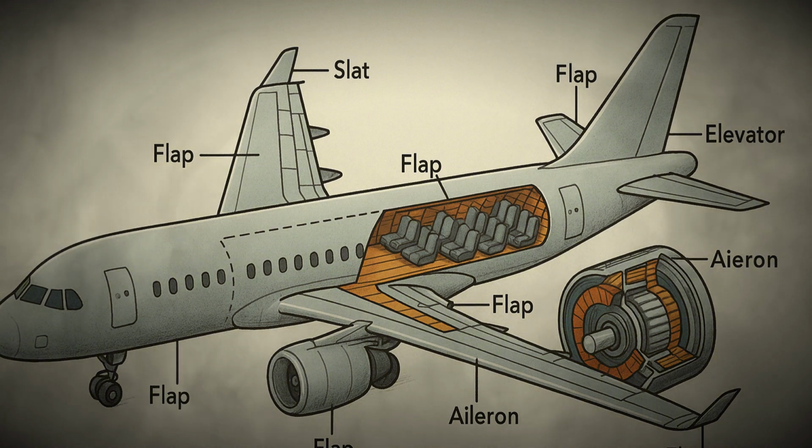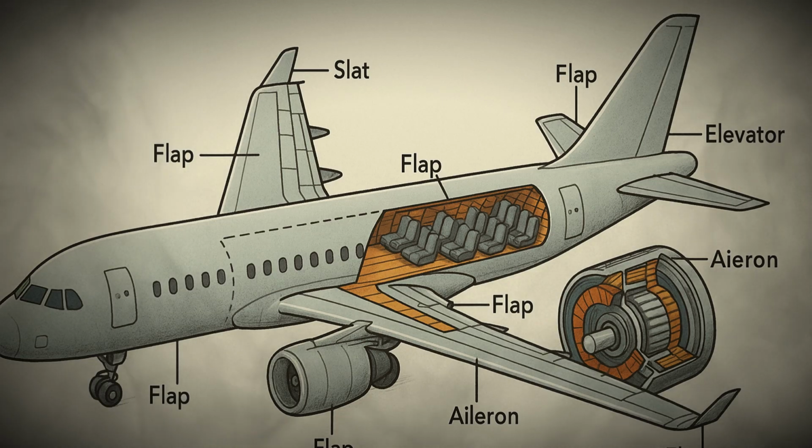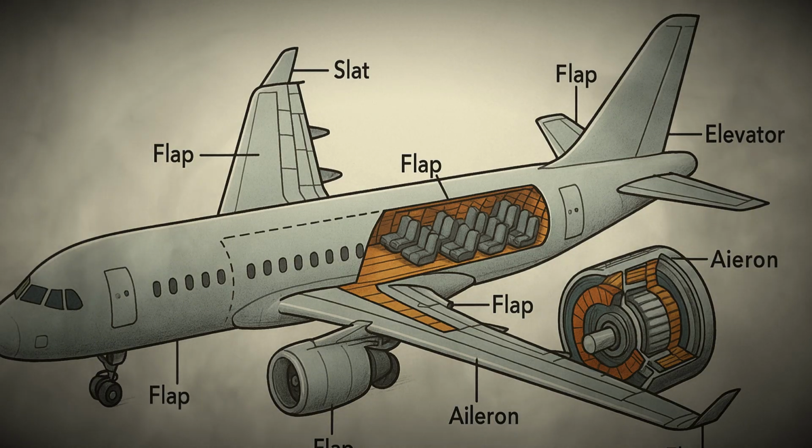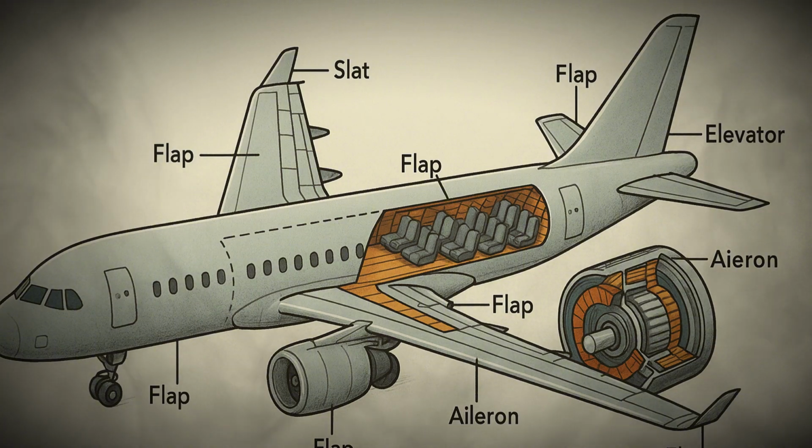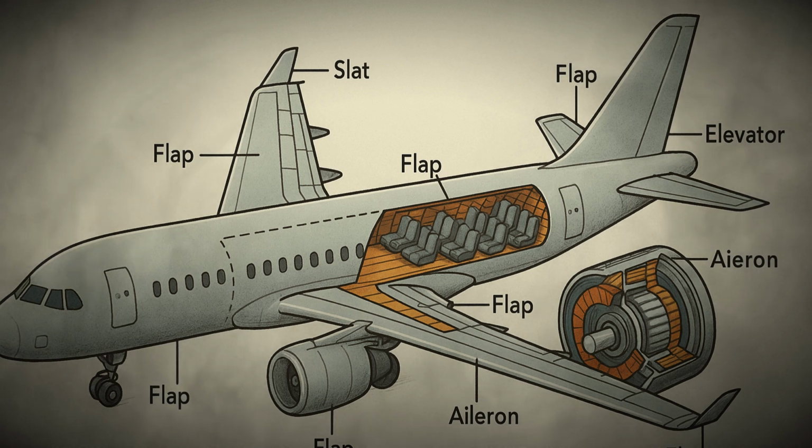During climb, sufficient thrust is required to overcome drag and gain altitude. At cruising altitude, engines typically operate at reduced thrust for efficiency, maintaining a balance where thrust equals drag. During descent, thrust may be reduced further or even set to idle, allowing drag and gravity to lower the aircraft, while at landing engines may provide reverse thrust by redirecting airflow to slow the airplane.